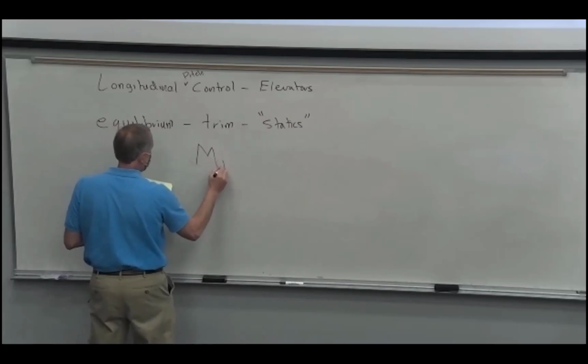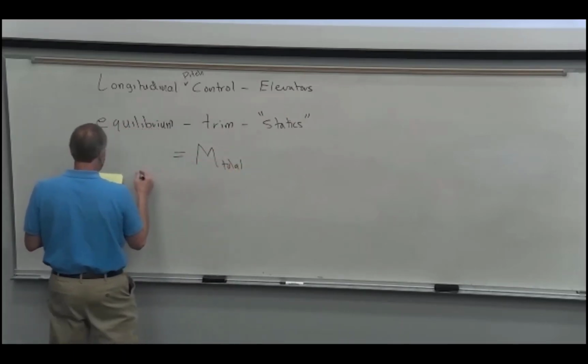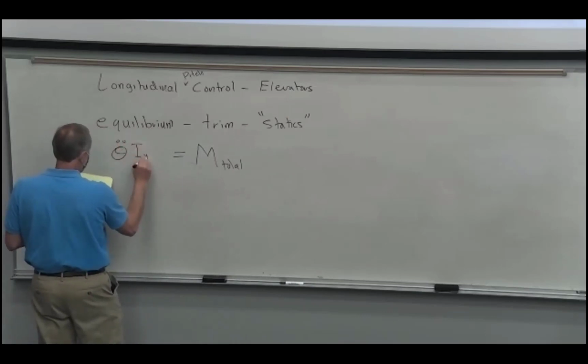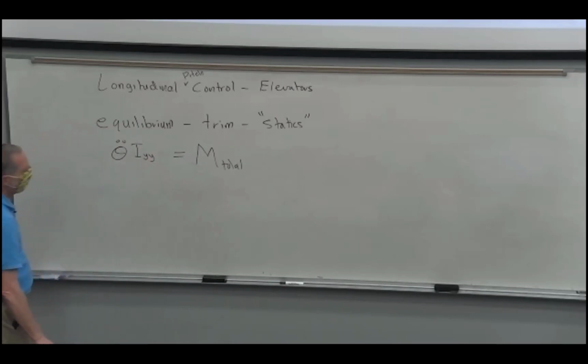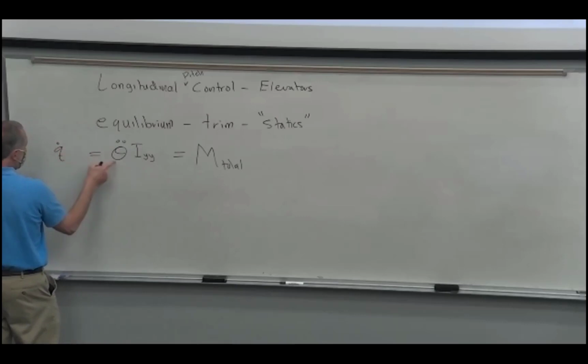this is the total, is the sum of the total moments, is equal to the mass moment of inertia about the y-axis, because that's what we pitch about, times theta double dot, or pitch rate Q is theta dot.